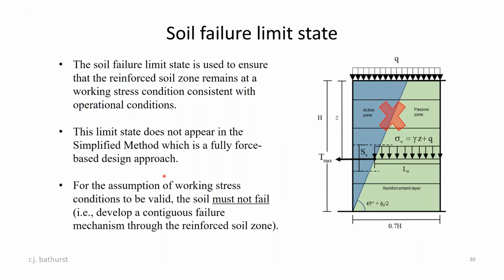It's very difficult to measure strains in the soil directly. But what we found was we could use the strains in the reinforcement as an indicator of whether the soil was at a limiting state. And knowing what that value was, we could then design our wall so that the strain in the reinforcement did not get high enough to encourage failure in the reinforcement itself, which would be manifest as a continuous failure mechanism or slumping or cracking at the surface.